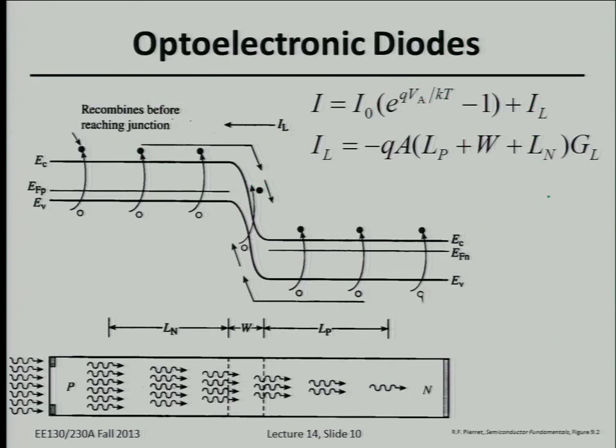Okay, that's another. Okay, so let's cover then the optoelectronic diodes, because that's probably most commonly encountered today in your lives. Okay, so an optoelectronic diode is just a PN junction diode. And what's shown here, is this under reverse bias or forward bias? Reverse, very good, all right. And we show, this is from the textbook Perret, it clearly shows that we have light shining on this junction.